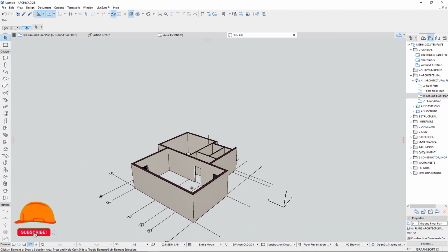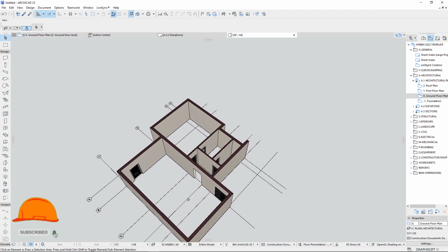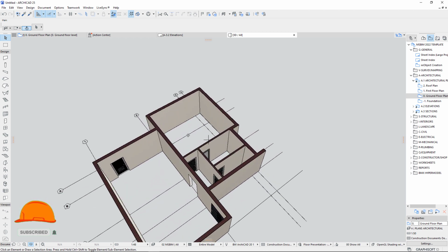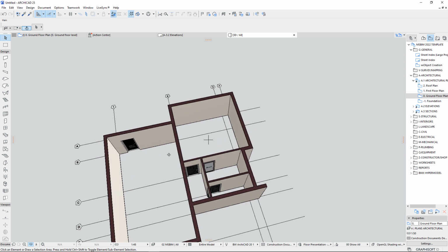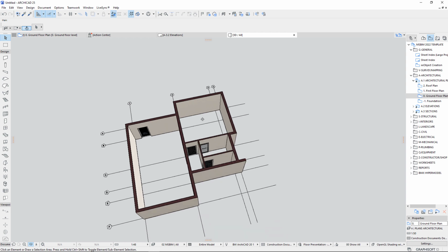So let's go back to our floor plan, and I think before we go for the windows, let's do the furniture layout, or what do you call the object layout. Let me just say furniture for this, so that you can have a guideline of how we're going to go about our openings. It's very important because you cannot have a bed in front of your window. So these are things that you need to take care of when you're designing. I'm not teaching you how to design here. I'm just teaching you how to use the software to achieve your design goals.